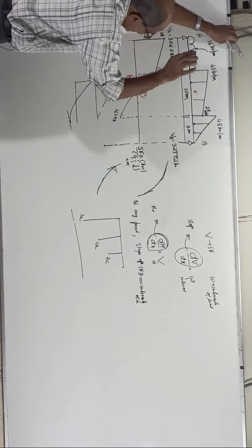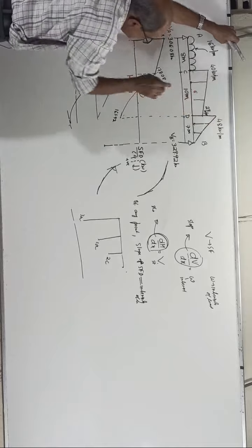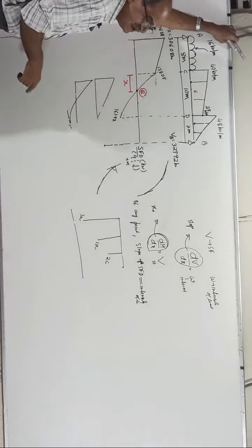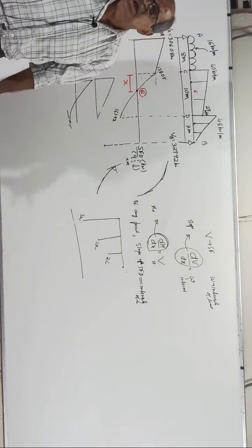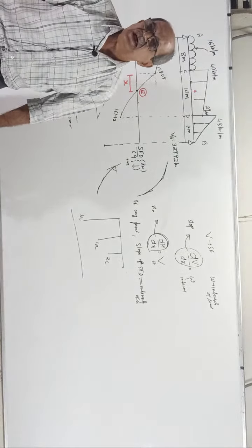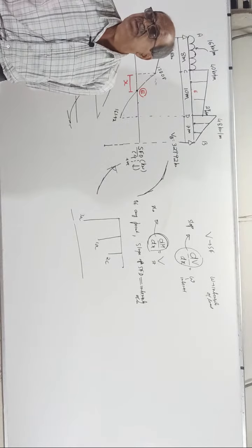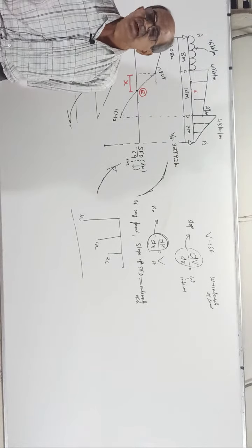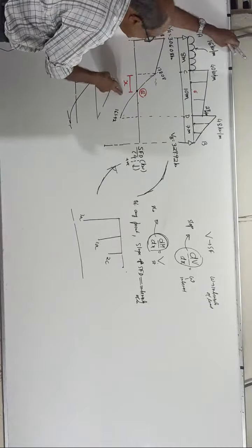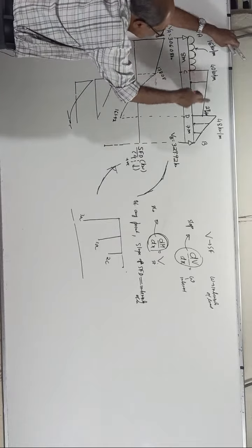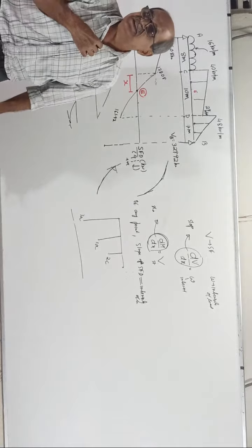Okay, now, one more thing. Suppose it is 40 to 38. It will be almost like a straight line. Even then, technically it is wrong, but X will come very near to correct. In structural engineering, especially mechanics or SOM or structural analysis, you never make such mistakes. In RCC, people will tell, almost okay, take linear variation because both are almost the same intensity. So many approximations we make in RCC and steel.